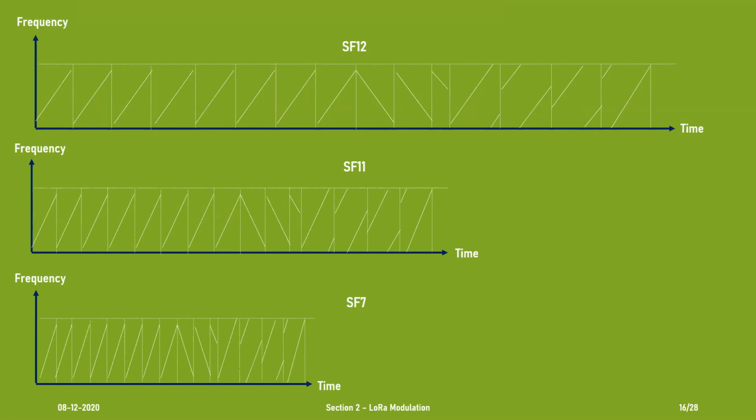So that's why when you see different spreading factor symbols, you see that higher the spreading, lower the data rate, because I'm taking more time per symbol and hence the total time increases. But since I'm taking a long time per symbol, it gets easier for the receiver to comprehend that signal. If you want to understand that mathematically, then we'll have to go into the depths of the CSS, because with a higher spreading factor there is a processing gain that gives you a low bit error rate and a small SNR, but that discussion is separate.